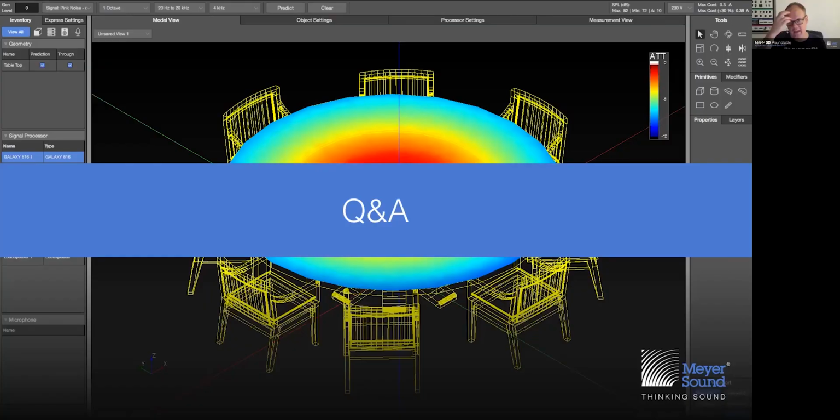Thanks. If we apply a boost, then we're likely to expedite the onset of nonlinear behavior. Whereas if we apply a cut or start reducing bandwidth, then it's the other way around. It's likely that some decibels might be left over on the table, but that behavior is currently not reflected in MAP3D. No. If you think about real headroom for real loudspeakers, it really is a frequency by frequency basis. Let's take a little speaker where it overloads at 60 hertz, which is very different from where it overloads at 600 hertz and where it overloads at 6 kilohertz in terms of SPL numbers. So it's a complicated subject.